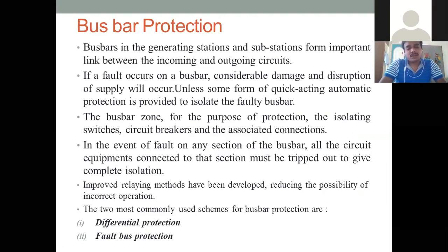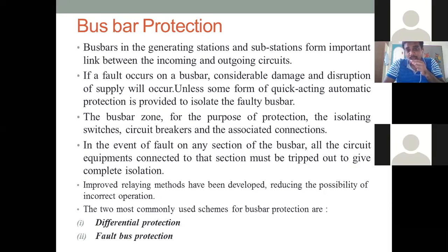Now all these alternators will be connected to a common bus bar. Similarly at the substation also. From the bus bars only, the feeders will be taken for the different connections to the distribution transformers, or it will be connected to an LT line or maybe an HT line. So bus bars are present both at the generating side as well as at the distribution side. Both the areas it is possible.